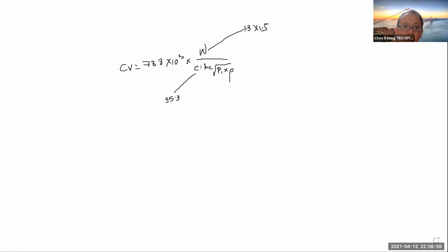Right? Now KC has another formula, right? So what is the KC formula? The KC formula, again given in the data sheet, is 3417 over CI, I think, and then multiplied by the square root of delta P over PI. Delta P over PI, rho or PI? Over PI.